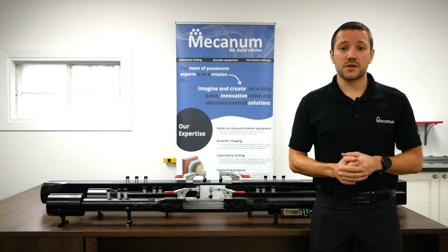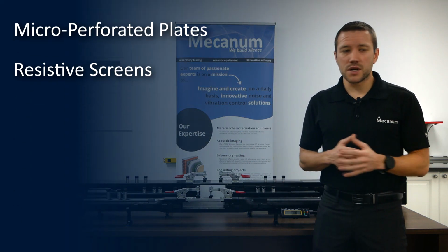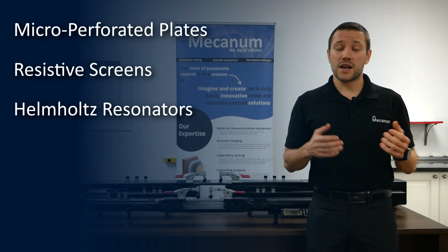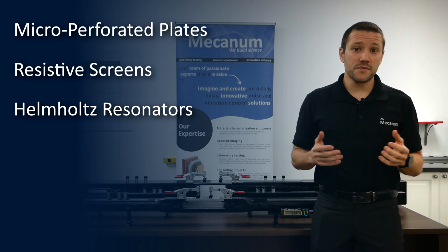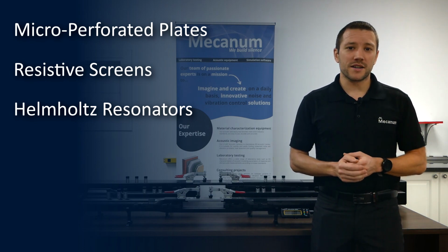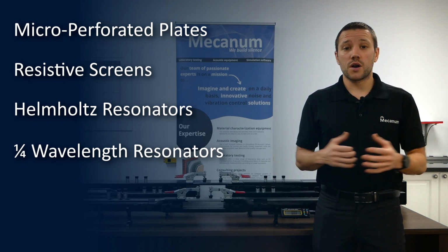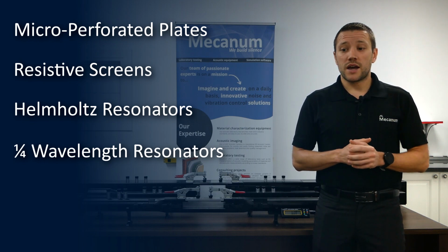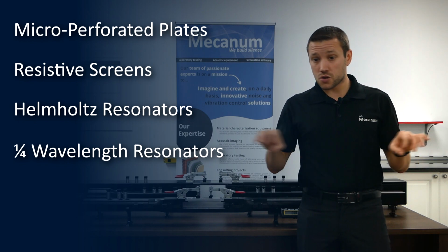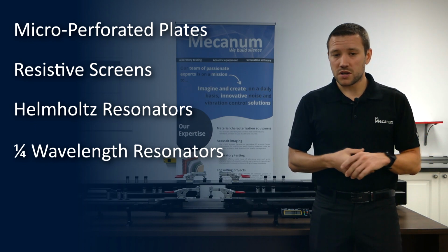There are many answers to this question. Of course, you can use micro-perforated plate, you can use resistive screen, Helmholtz resonators, which are actually a pretty old solution. They were invented in 1850 by Mr. Helmholtz himself, and now they are being revisited in many articles. It's the same thing for quarter wavelength resonators. Quarter wavelength resonators are also a pretty old solution, but the interesting thing with them is that they don't necessarily need to be straight.